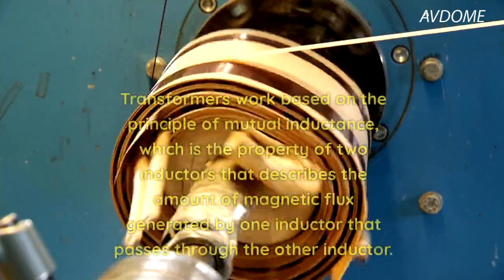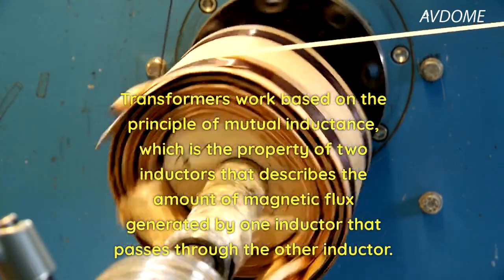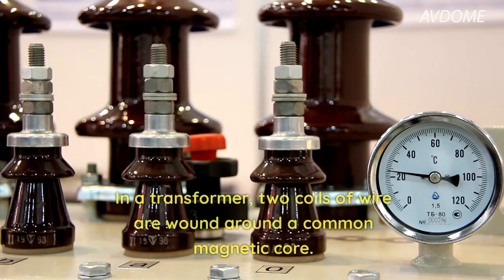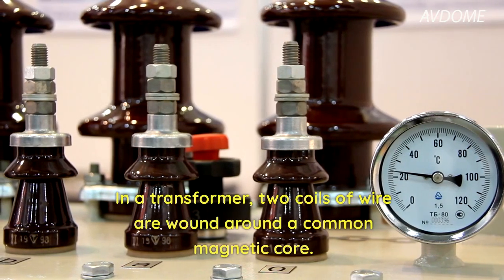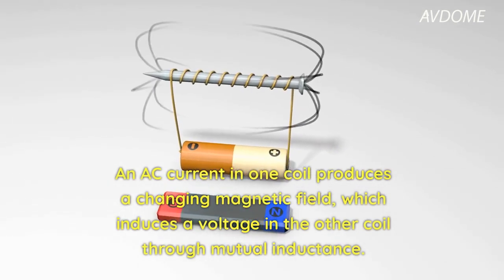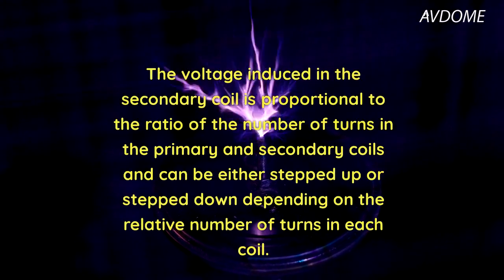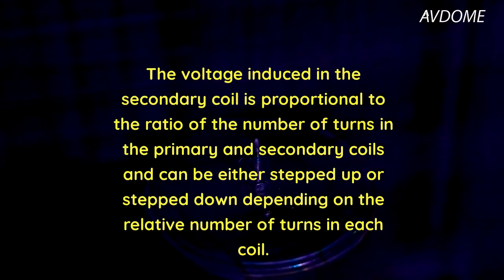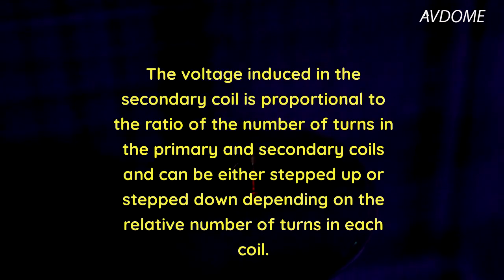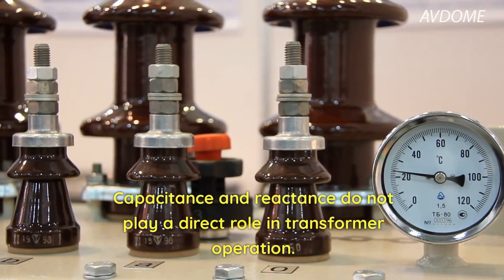It is A. Transformers work based on the principle of mutual inductance, which is the property of two inductors that describes the amount of magnetic flux generated by one inductor that passes through the other inductor. In a transformer, two coils of wire are wound around a common magnetic core. An AC current in one coil produces a changing magnetic field, which induces a voltage in the other coil through mutual inductance. The voltage induced in the secondary coil is proportional to the ratio of the number of turns in the primary and secondary coils and can be either stepped up or stepped down depending on the relative number of turns in each coil. Capacitance and reactance do not play a direct role in transformer operation.